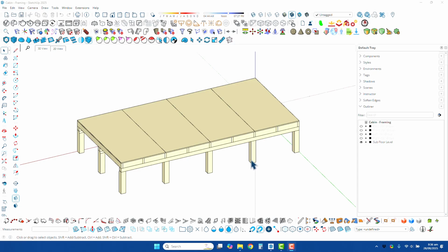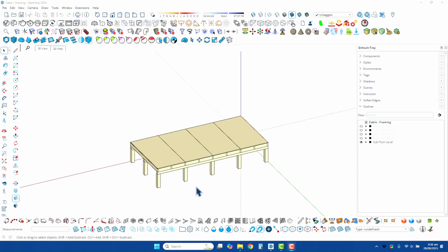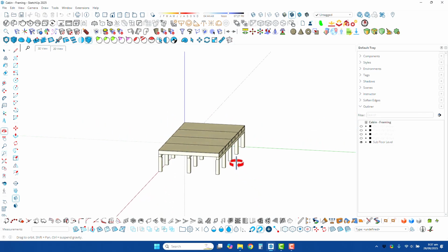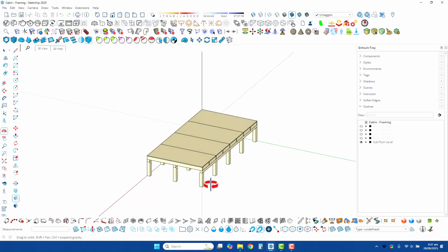My name is Russell Elliott and I'm going to be taking you through a few tools today to help you create raking walls. The tools are the tape measure tool to create some guidelines, the protractor tool to create angles and guidelines, and also the rotate tool, which will help you to manipulate and rotate members to the required rakes and pitches that you want. We'll also have a look at reinforcing some of the things we've learned with grouping and the outliner filter.